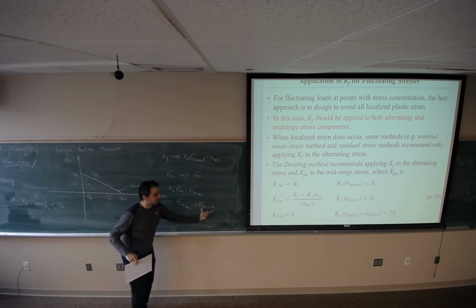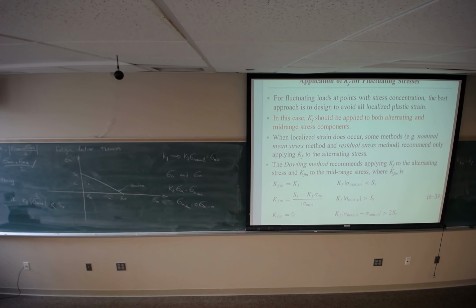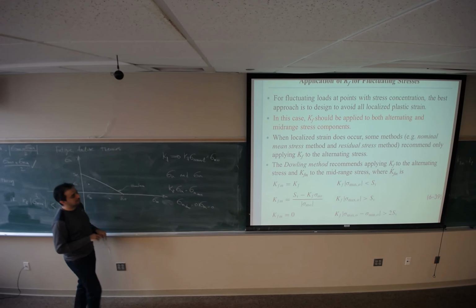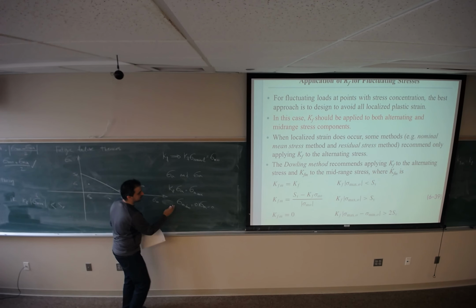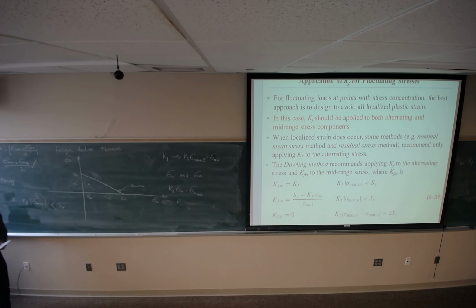So make sure that you apply Kfm if you have any discontinuity on the component, and this is how you can apply Kfm. For Kf, for sigma A, it's obvious: you find Kf, you multiply by sigma A, and you will find sigma A max. But for Kfm, or for the mid-range, it's going to be different, so you have to find Kf first. This is one important thing that you should consider when you do the stress analysis.